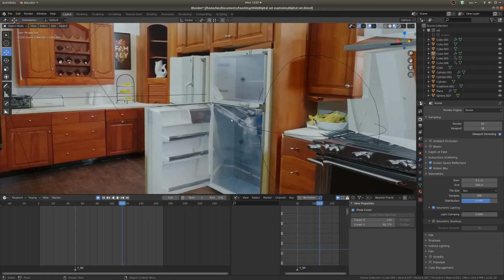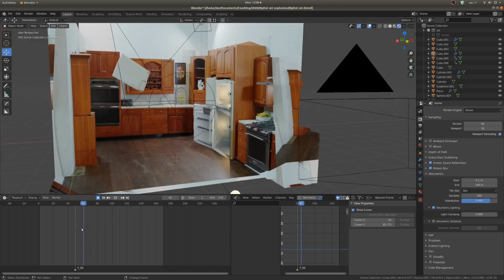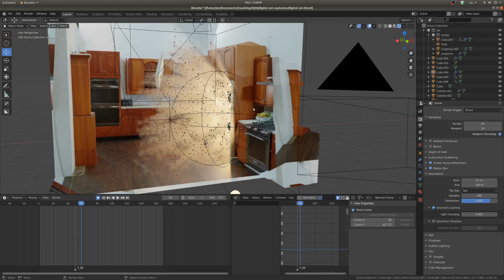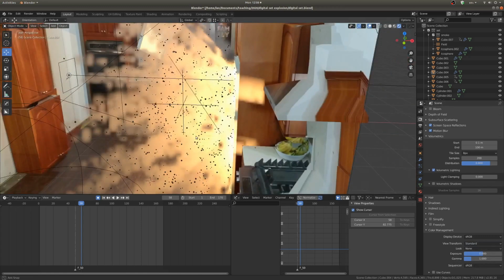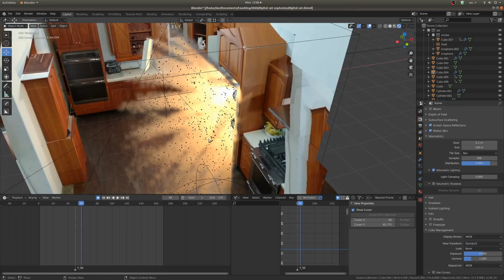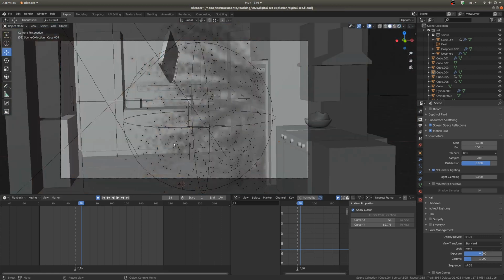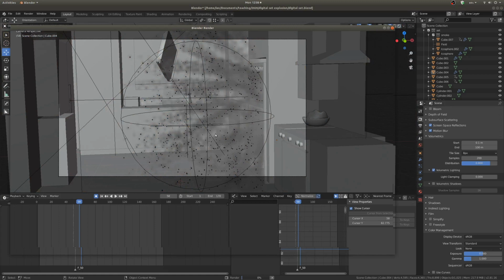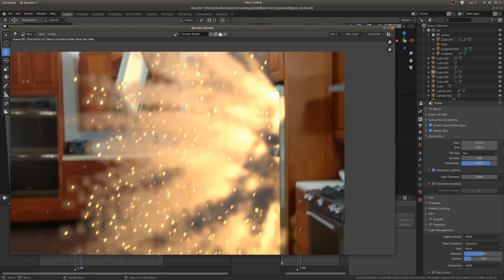Cool. One more thing that I have been experimenting with and I kind of like the look of is going, let's get the smoke back, in the render settings where I've got the volumetric settings as well. If you go down to color management, it's usually set to filmic, and I found setting it back to standard actually got an explosion that I like the look of more than with filmic. And I know there's probably reasons why I shouldn't do this, but I'm doing it because I like the look of it. So if we render here, you can see it's a really aggressive, fiery, clipped out explosion.